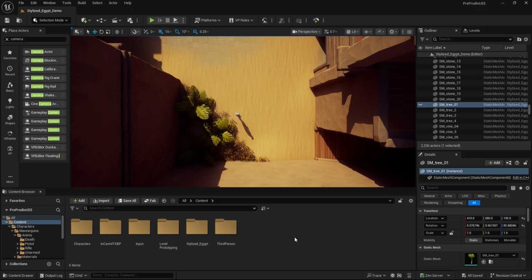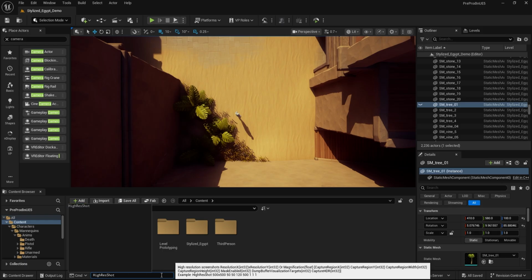It's easy to reposition and it's easy to hide assets within the viewport, and you can choose whether to have gizmos displayed or not. On the other hand, the viewport camera is not a true top-down view. It is a perspective view and as such is not truly accurate. An image created this way would work nicely as a visual reference, but would not truly be usable for situations where accurate measurements need to be made. Moving on to the second option.